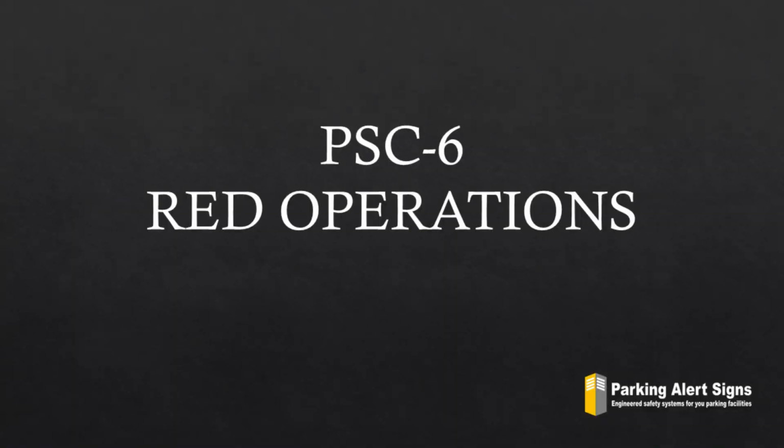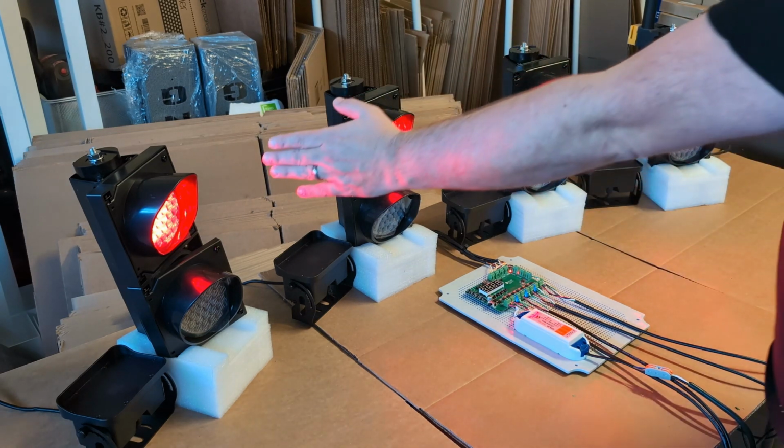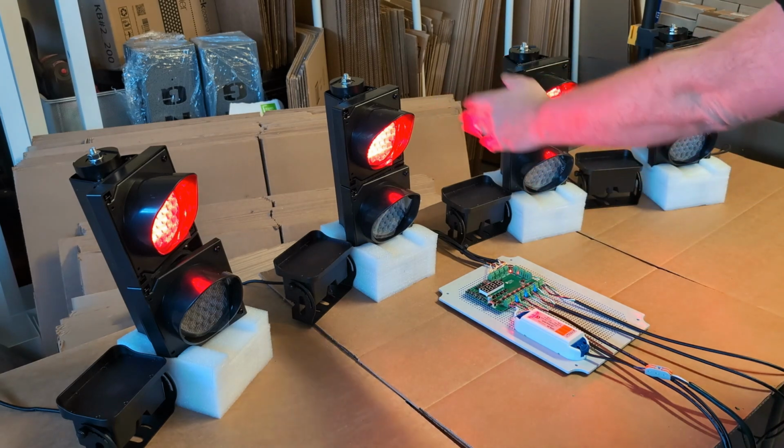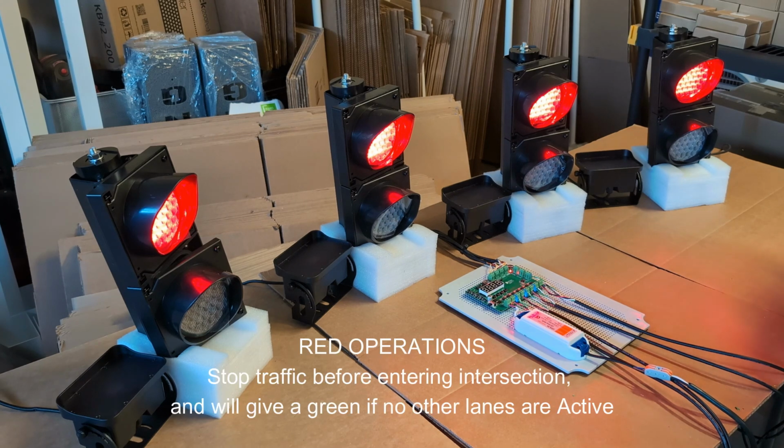Operations. Let's see our setup here in action. I have set up vehicle motion detectors to activate from my hand, simulating detection of a vehicle. Let's picture this setup as a four-way intersection. We have our north lane, east, south, and west lane. Red operations is designed when you want to stop traffic before an intersection and then provide a green light when the traffic is clear. Here I'm going to simulate a vehicle is detected.